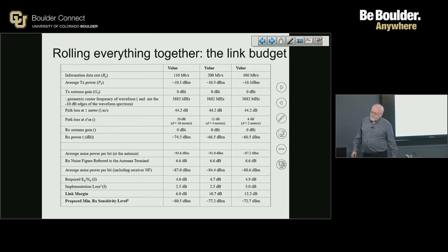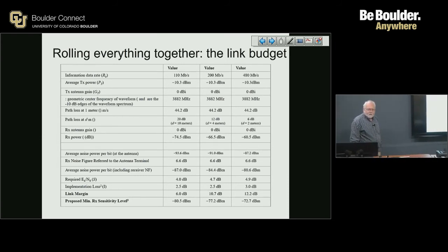So what you can't allow is your link margin to get less than 0, right? If your link margin is less than 0, then your link doesn't work. You can't meet your design constraints for your system. So link margin always has to be bigger than 0, or your link won't connect.